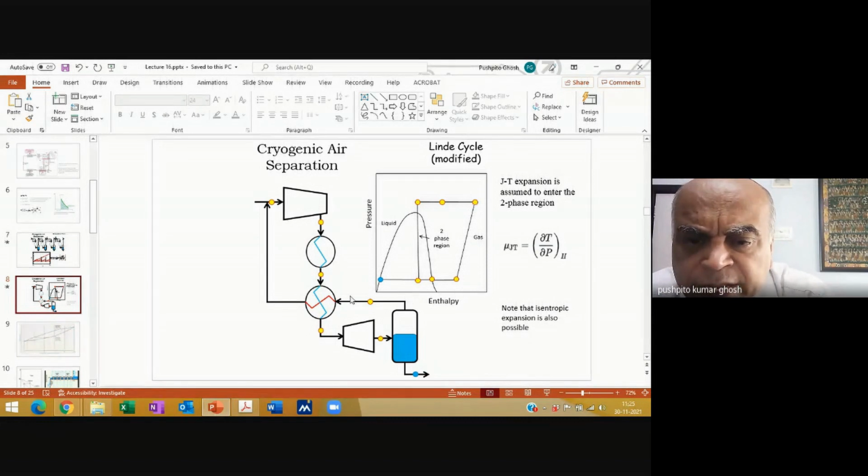Now what I'm doing is I'm just cooling it with water externally. So I'm reducing the temperature, so I'm bringing down the enthalpy. Now I am also utilizing some cold streams, and I'll describe those cold streams to you. Some cold stream is going past, and so my relatively warm stream gets cold. So the enthalpy dropped further and it came to this point.